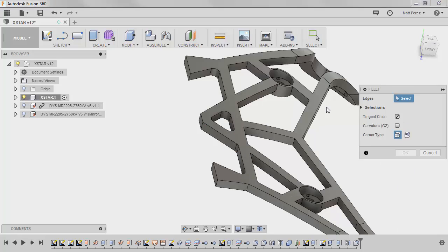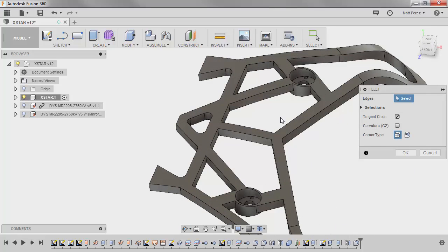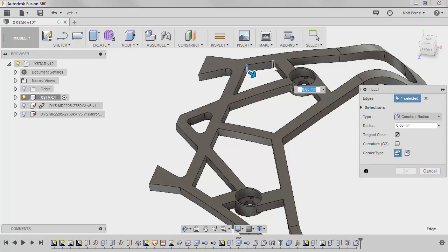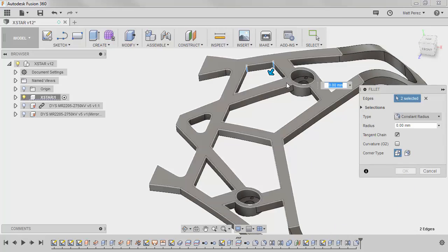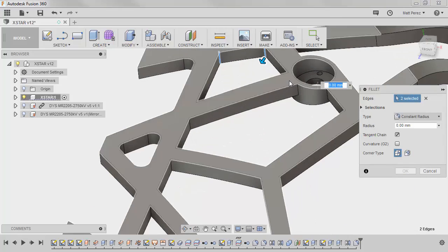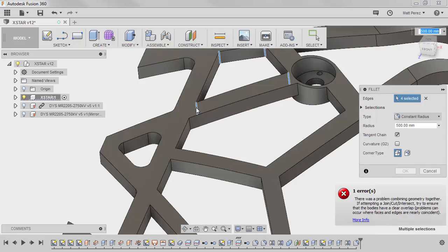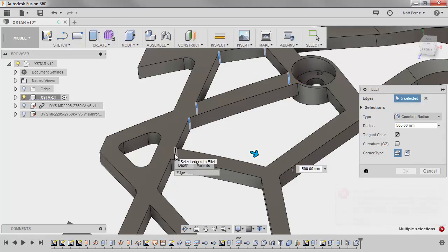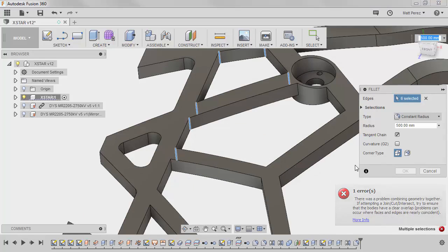We're going to use our marking menu to repeat that by holding down the right mouse button and dragging straight up. And then we're going to start to collect some of the edges in these internal sections as well. Now again, by default, it tries to grab the face, and depending on where you're selecting, it might be easier for you to come in and actually hold down the left mouse button to get the selection.